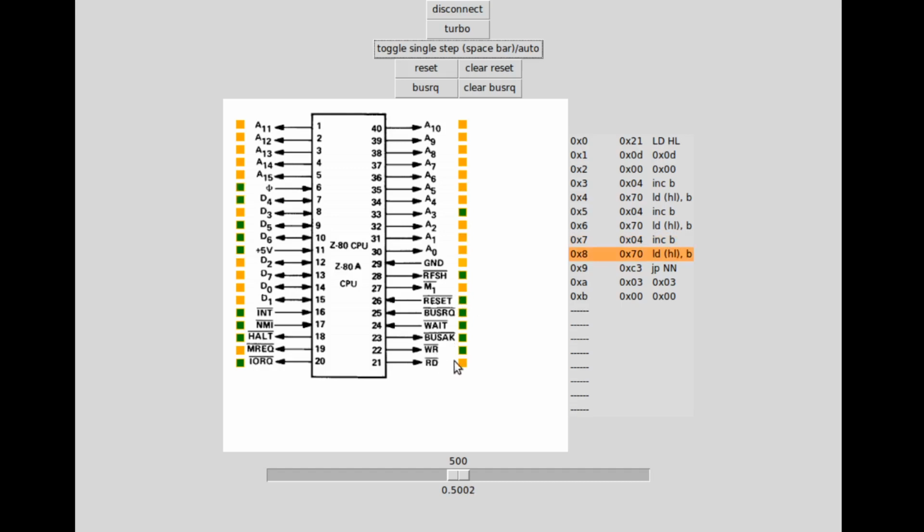And here are the write and read flags that the CPU puts out. So when write goes low, then that's when the red shows, because it's writing to memory, and then when read goes low, it's either going to be orange or yellow. There's yellow there, because it was a read, but it wasn't an M1 operation. When refresh goes low, then it's just reading the memory just to keep the dynamic memory remembering. It's not showing the refresh at the moment because I think the refresh address is too far. What is it? It's about 16 and it goes off the end there.